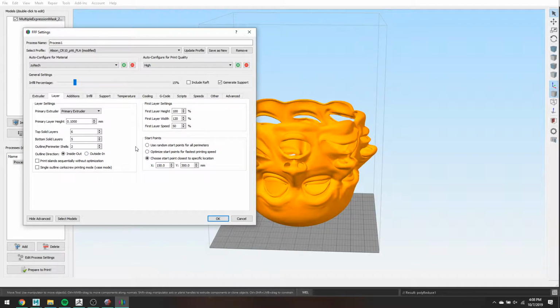I think they also have an option for that in Cura. In general, I personally prefer to do inside out, just because it usually goes a little bit better quality on the outside. It also sort of helps for overhang. Like if it's going to have ugly areas, it does that on the inner layers. So by the time it gets to the outside, it has something to sort of tack that plastic onto, if that makes sense. Honestly, both work fine for most models.